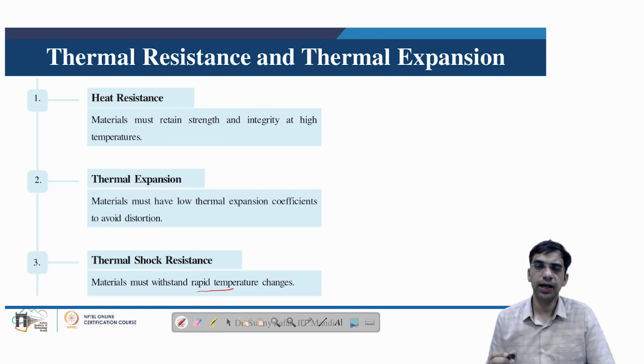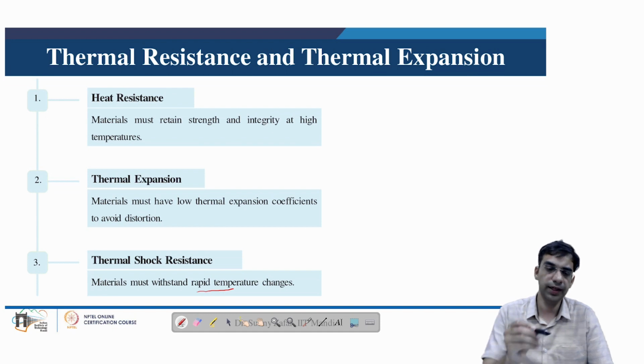For example, a ductile material at room temperature may suddenly act as a brittle material when exposed to ultra low temperatures, which is characterized by the ductile to brittle transition, and such materials become difficult to manage if the operating conditions require a change in temperature while the product is functioning.